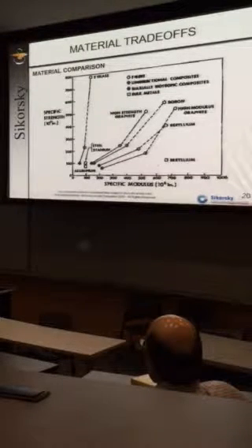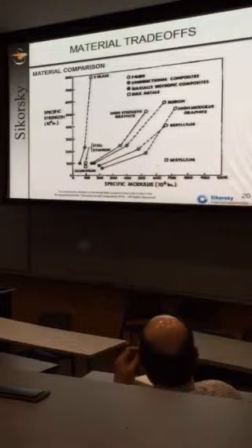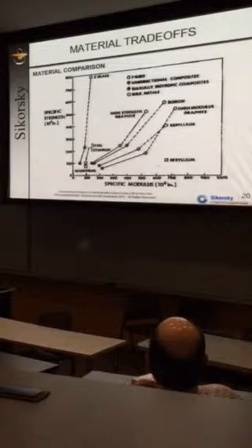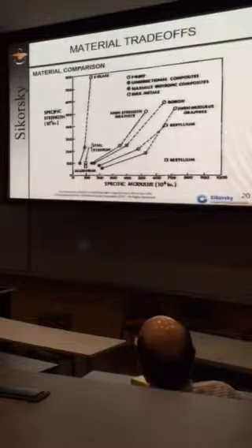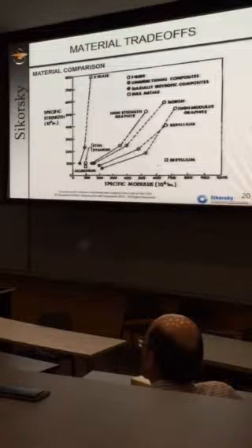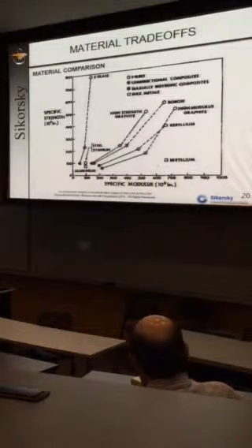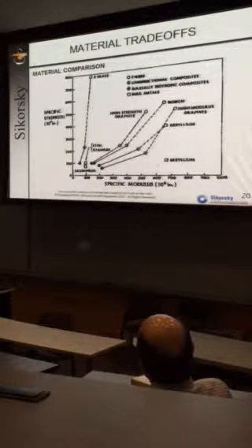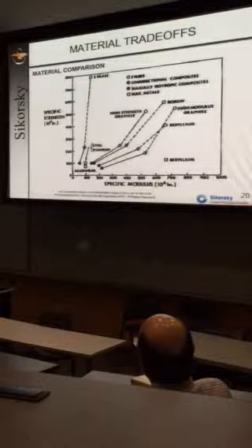So despite all the mechanical properties that beryllium affords, we don't use it because of that third dimension of that triangle that made the pyramid, the environmental aspect of it, where there are a lot of great materials. Asbestos is great for insulation. Beryllium is great for optimum stiffness. Chromium is great for corrosion resistance. But you've got mesothelioma, you've got berylliosis, you've got carcinogen and hexavalent chrome. So those are all things that we need to consider when making a trade.